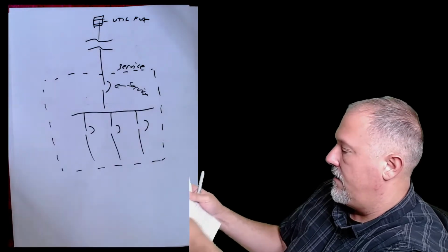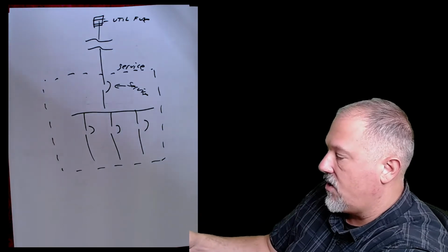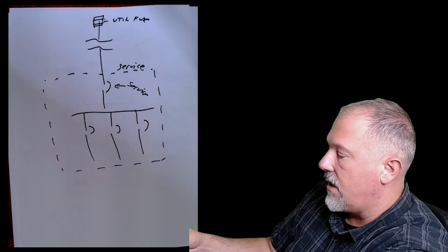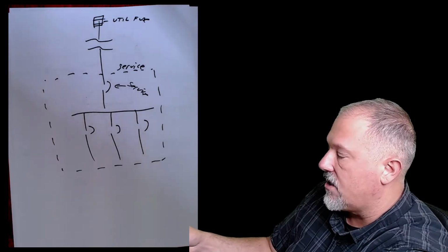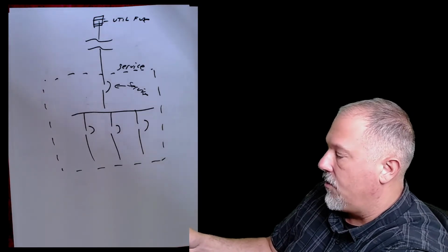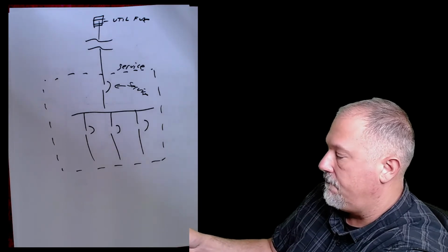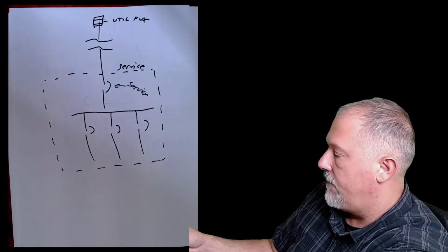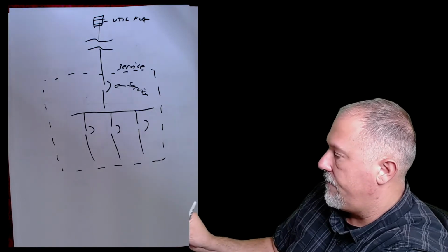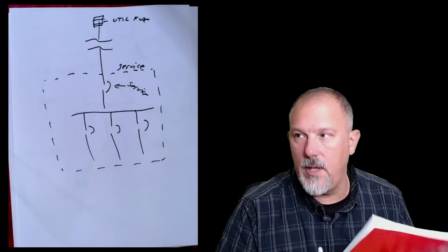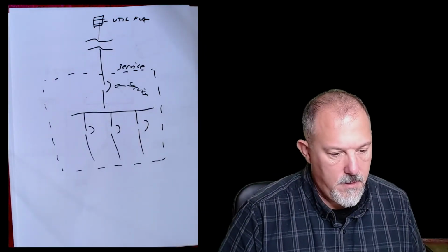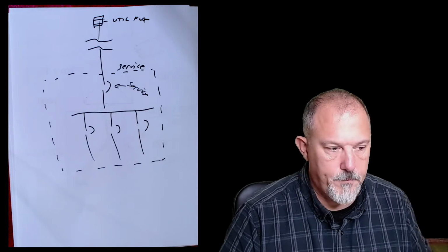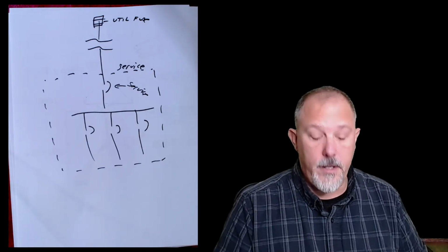Equipment labeling. Electrical equipment such as switchboards, panelboards, industrial control panels, meter socket enclosures, and motor control centers that are other than dwelling units and are likely to require examination, adjustment shall be marked with a label containing the following information: nominal system voltage, arc flash boundary, and at least one of the following, the method of calculating. So I think what your issue is, Ryan, is that we don't know what an arc flash label is. And you might be right.